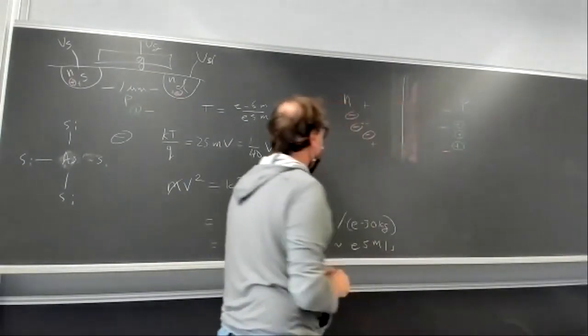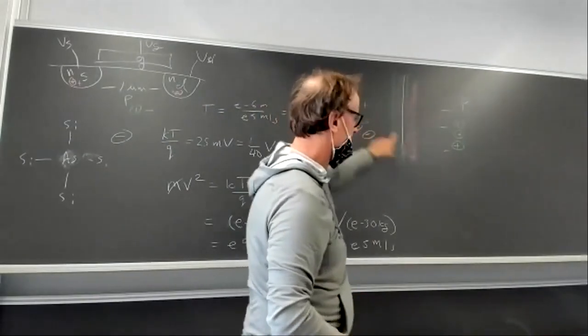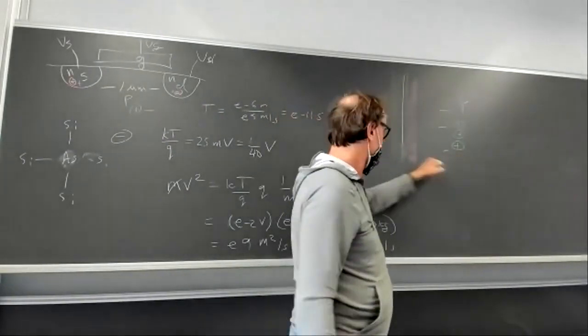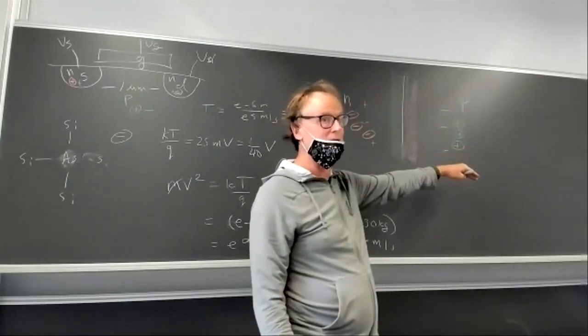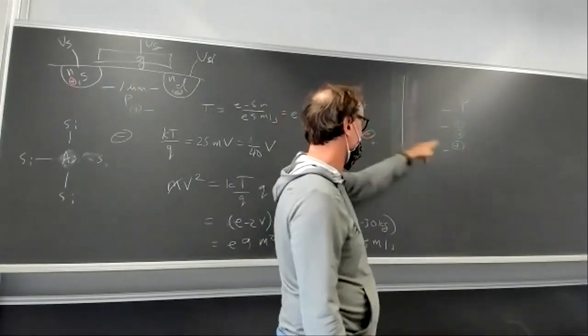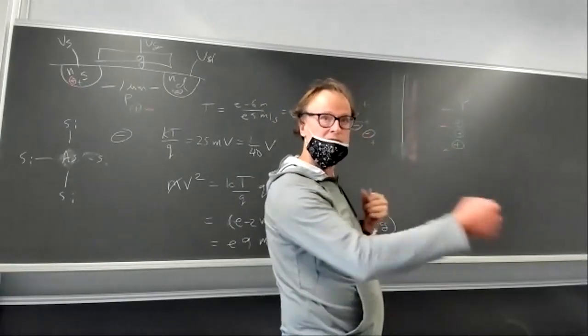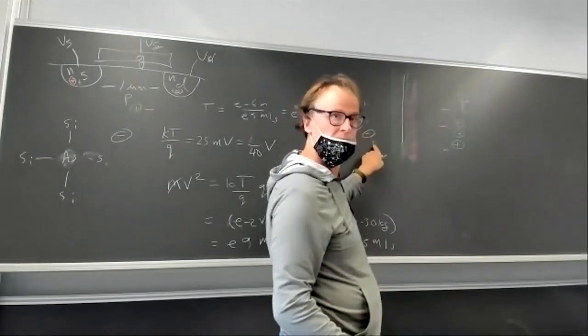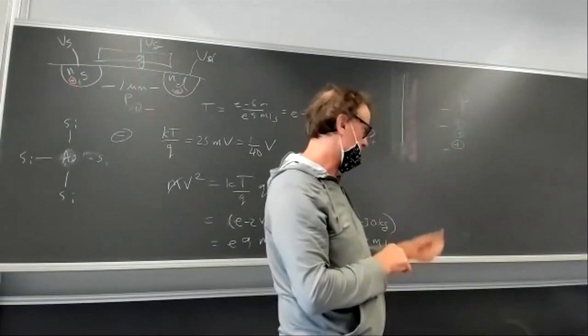Okay. So now because of this concentration gradient of electrons, lots of electrons here and very few here, the electrons are going to rush across to this side. That can't go on. As soon as an electron rushes from here to there, it leaves behind the positive charge. And there's an attractive force between this negative electron and this fixed positive charge. So that builds up an electric field pointing back. It'll pull the electrons back.